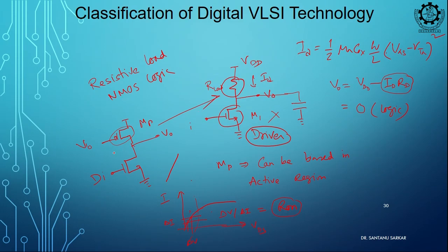So, this can replace this resistance. This is called an active load. This was a passive load. I just replace this, and the input is given to this. So, this still remains my driver, but this is an active transistor, and this voltage is not my input voltage; it is a fixed DC voltage. So, this will behave like a load, clear. This is known as the active load, clear.